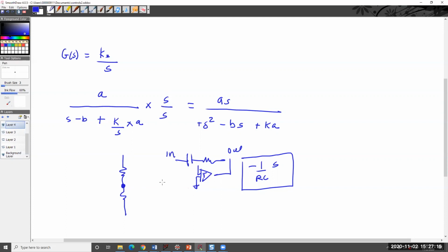If I had asked the question, find the simplest way to fix this being out of control, then proportional would have been the best answer and the only answer. But if I said, can you make this transfer function in control, and you used ks and then came up with the right conditions, it's right, and it should be marked as right. I might forget that, and then you just have to tell me.